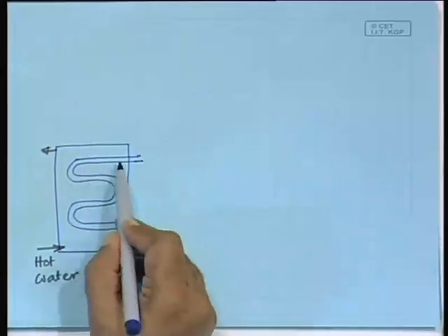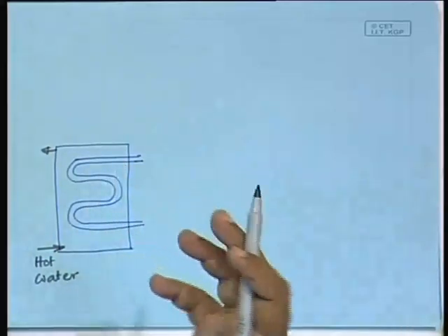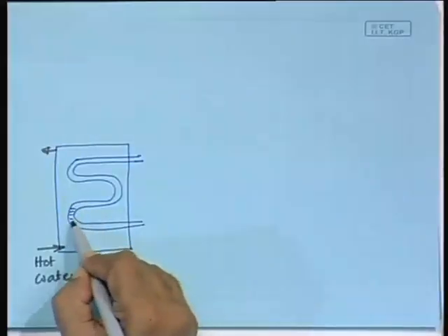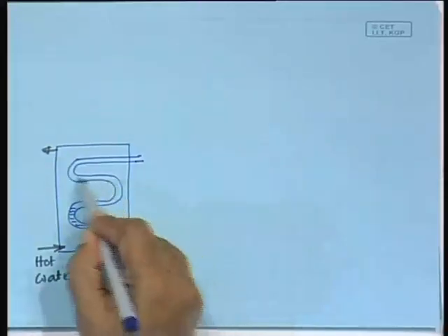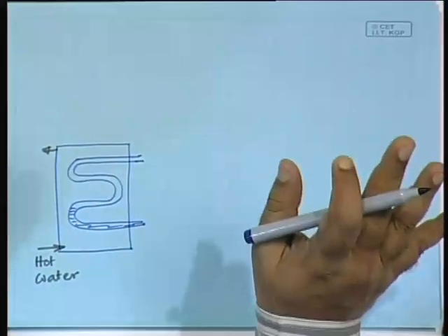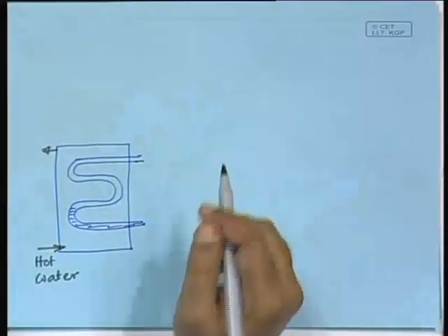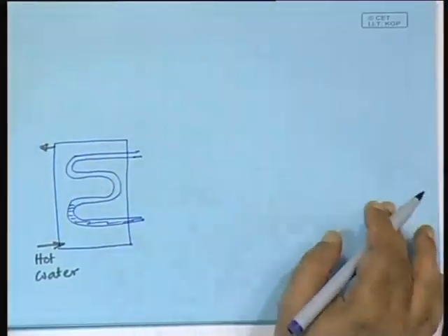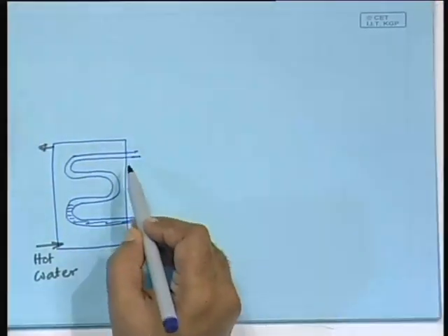At this stage what is produced is basically saturated, right, because it is in contact with the liquid. Liquid may go up to this stage, and as it goes up it becomes gas, but nevertheless saturated. So, there would be saturated ammonia vapor. Saturated means there would be tiny droplets of liquid, and so that has to be separated out before it is fed into the turbine.